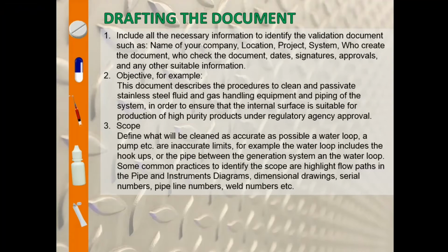At this point, we have enough elements to create a passivation validation package. The validation package should be unambiguous and clear. There should be no room for questions about what was passivated, the location, when and who was involved. If those questions are not fully answered, or indeed there is a doubt or fuzziness with the interpretation, the validation package is incomplete.